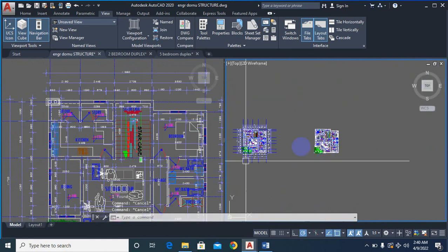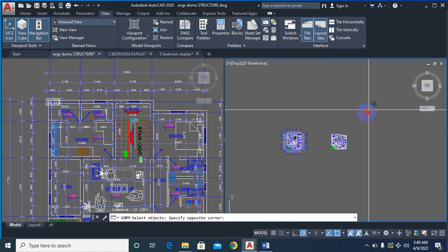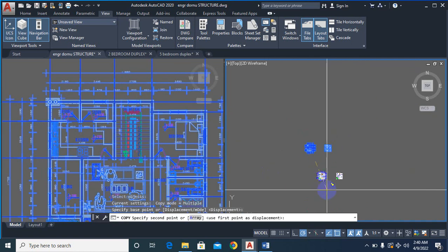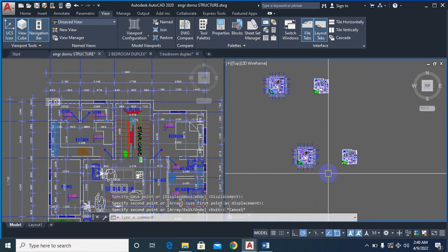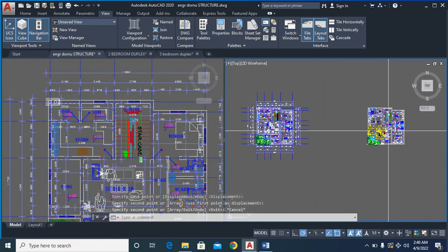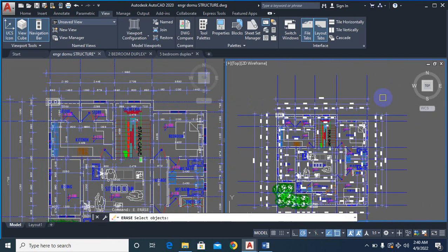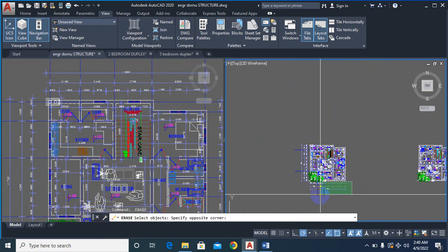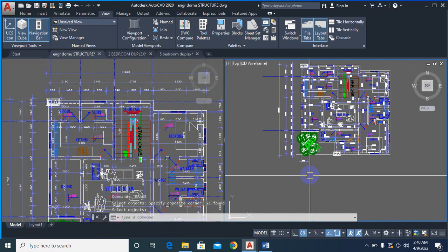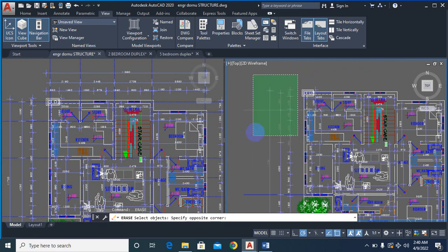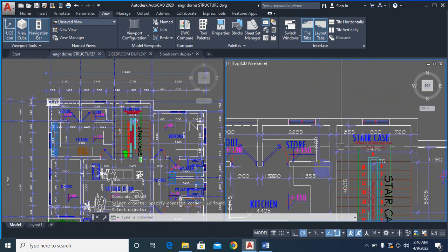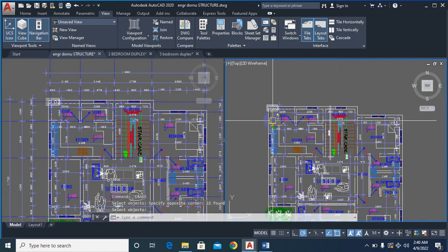Sorry, I always like to copy and have a duplicate copy, because I will always go back to make reference to the architectural drawing. So you always take out your doors, your windows, you close every opening. There should be no opening in your drawing.